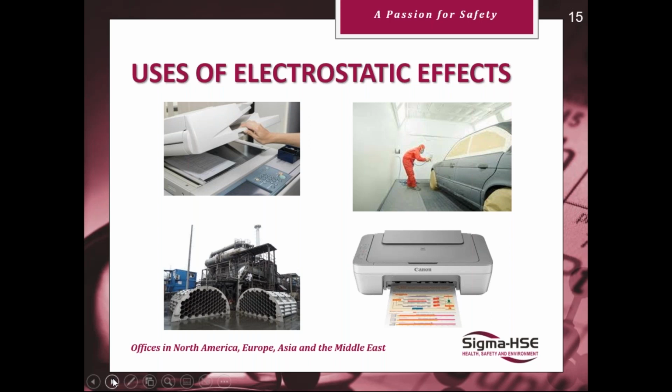If you look at static precipitators there, again, they're using electrostatics in a very useful way. The same with the printer, they're there. If you look at powder coating, which is getting very popular within the car industry, then again, to put the powder onto the metal object, they use electrostatics to do that, to give you an even coating again.